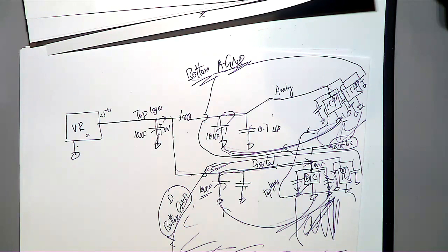You isolate all the grounds, and then on the top what you can do is you can put ferrite beads, tantalum capacitors, so that you are suppressing the noise. But in the ground you can put a net tie. But if I put a net tie everywhere, then you will forget about the use of isolation ICs. So that's the reason in DSO design, when you have 4 blocks, in one place we will be using an isolation IC. And then I'll show you.